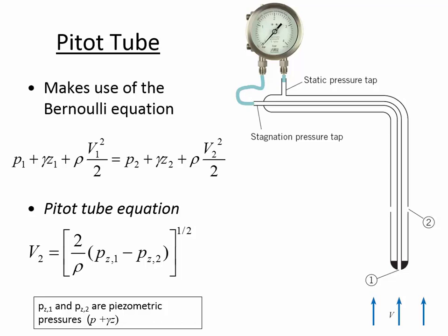At the same rate that we were losing Z, pressure is increasing by delta Z times gamma. So here's the delta Z between the 2 points. That's for static conditions. Here, when we have a pitot tube going through a gas or a liquid, then there is a change in piezometric pressure. And so the pitot tube is measuring that.